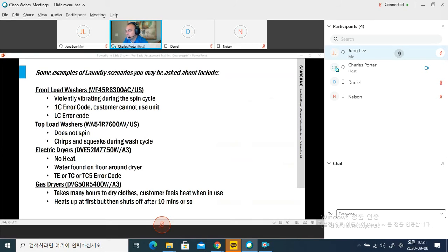Next, you're going to go to the terminal block on the dryer, and you're going to look for the same thing. You're going to look for 240, L1 to L2, L1 to neutral, 120, L2 to neutral, 120. All right, you want to check it at the dryer too, because you want to make sure that power cord is sending that power through there.